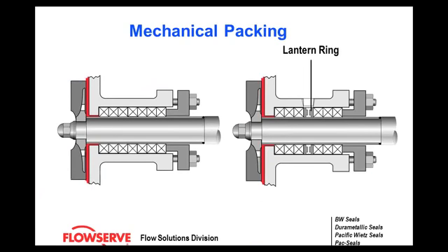Now, before mechanical seals were developed, the typical way to seal a pump was with packing. Packing was a fibrous material that was usually impregnated with some sort of lubricant like graphite, and cut into sections, stuffed down a stuffing chamber, stuffing box, and then a packing gland was applied on the backside to tighten everything down. Now I'm going to show you with my cursor that right there, item in gray, that is the packing gland.